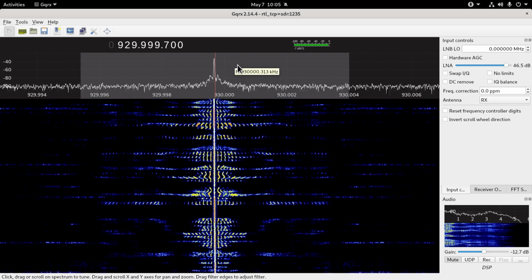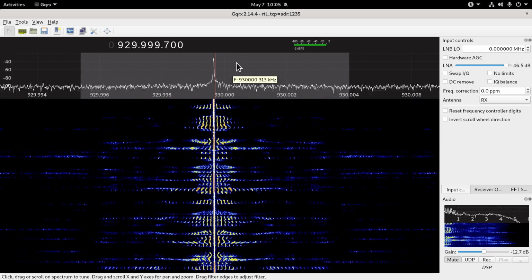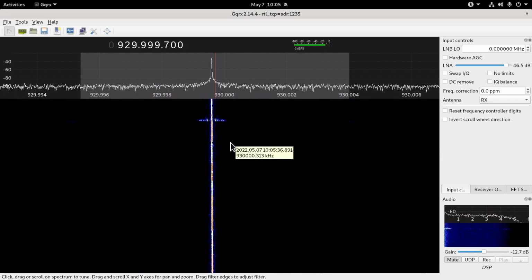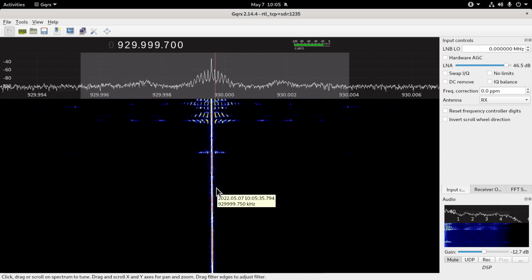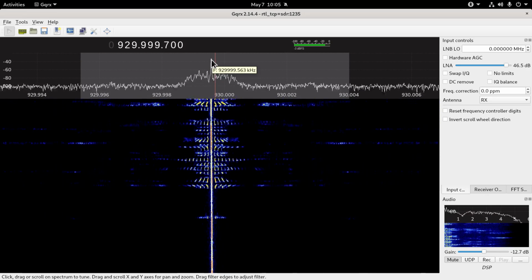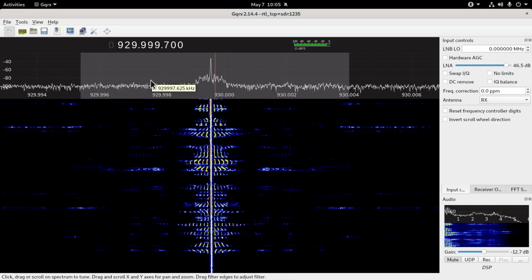This part here is all you really need for all the information I'm sending, which is the baseband, my voice. See, that's me just being quiet for a bit, and what you saw was just the carrier. So the carrier is always putting energy out, and then when I start speaking, you get these sidebands over here.